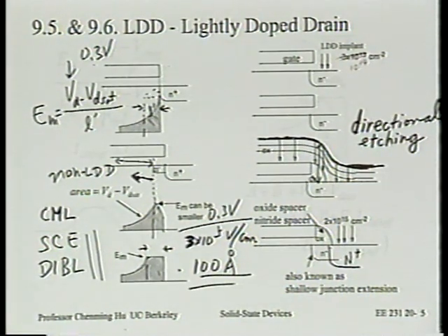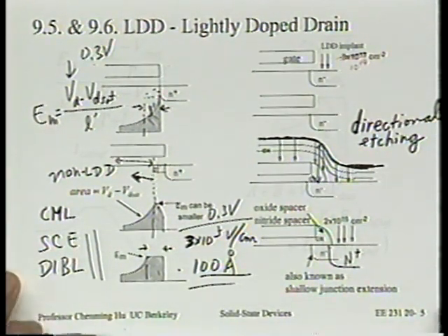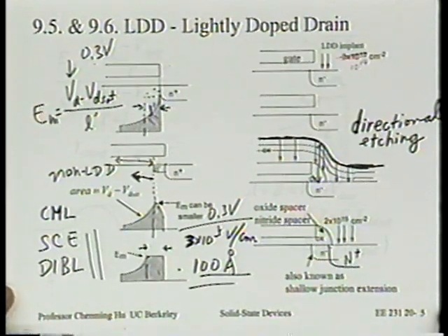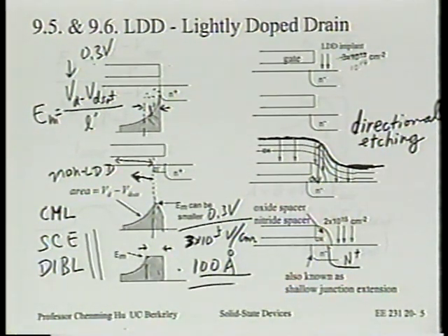So it seems like this above is the poly of the gate, right? So there's gate poly and then oxide. That stack is thick, by the order of what we care about, probably half a micron thick or so. So the radius of that oxide spacer left, if we looked at this even conformally, will be much bigger than 100 angstroms, or even the oxide.